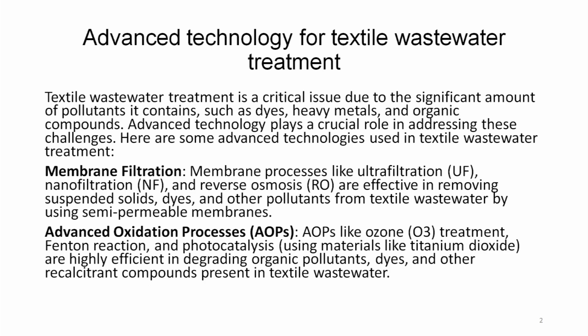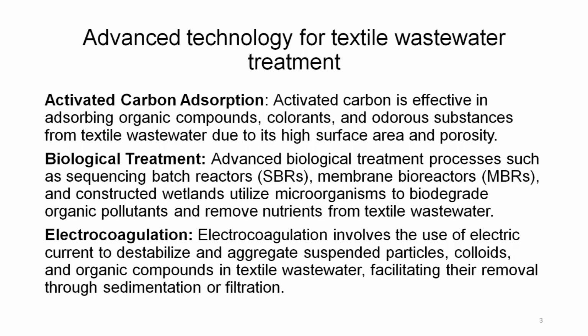Advanced oxidation processes, AOPs. AOPs like ozone treatment, Fenton reaction and photocatalysis using materials like titanium dioxide and zinc oxide are highly efficient in degrading organic pollutants, dyes and other recalcitrant compounds present in the textile wastewater.